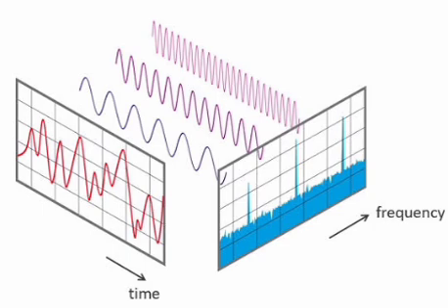For power signals, alpha of tau equals the limit as T tends to infinity of 1 by T times the integral from minus infinity to infinity of x of t x of t minus tau dt. Properties of the autocorrelation function: alpha of tau is even, alpha of tau equals alpha of minus tau, and alpha of 0 is greater than or equal to alpha of tau. For energy signals, energy equals alpha of 0. For power signals, power equals alpha of 0.